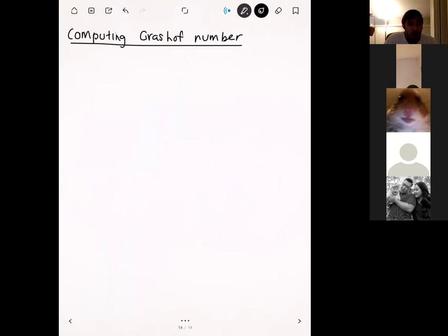Okay. And so let me go ahead and give you the expression here. I do have a derivation of this in the notes, but it's kind of lengthy and not really relevant for what we're doing. If you want to see the derivation of the Grashof number, you can see it in the notes. Basically, I go from Navier-Stokes and do some work to introduce temperature into Navier-Stokes, because Navier-Stokes normally doesn't have any temperature, right?